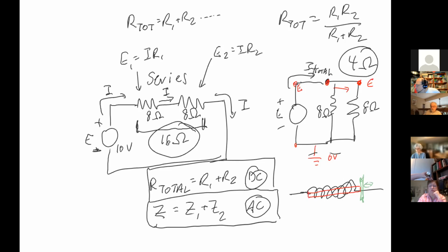So what does a speaker do here? As it moves back and forth and the diaphragm moves air back and forth, what does it make? Produces sound. It makes sound. Okay. But now what is the actual resistance of a coil of wire? Very small. It's just basically a coil of wire, but it's an inductor, is it not? Which means that it actually has an impedance. So the impedance of a speaker would typically be listed as something like 8 ohms.